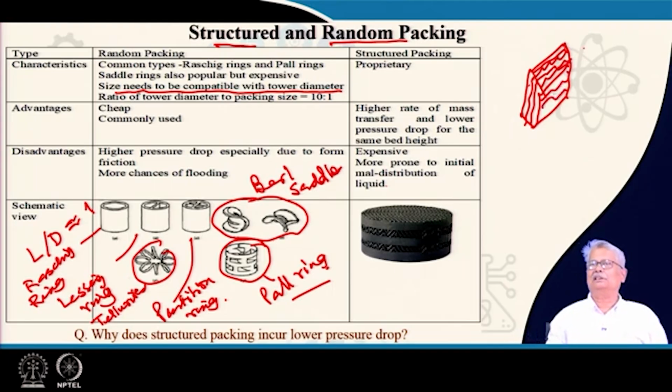They are vertical corrugated sheets, and these blocks can be placed side by side, or one above the other. One good thing about placing these blocks one above the other is you can almost align one block's outlet with the inlet of the block above it. That means there is less deviation in the flow direction of the fluid, basically the liquid and the gas both, as it flows from one block element to the other.